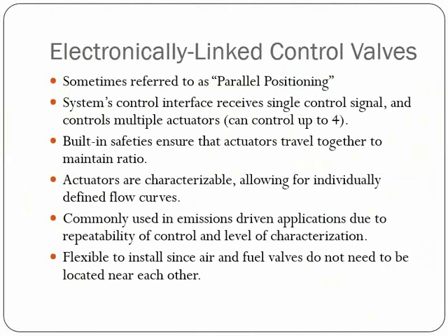So there needs to be feedback to the control interface to let it know that the air valves and the fuel valves are in the right position and are traveling together. So we've got built-in safeties to ensure that that happens and maintains the ratio.